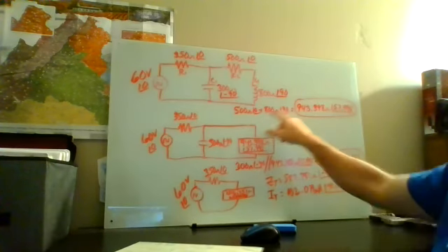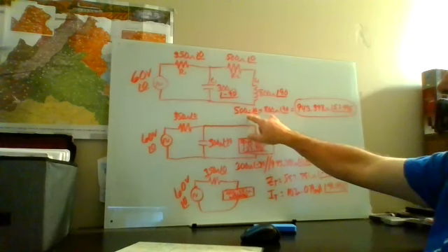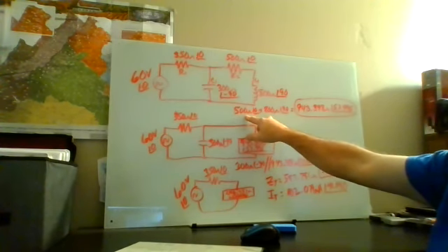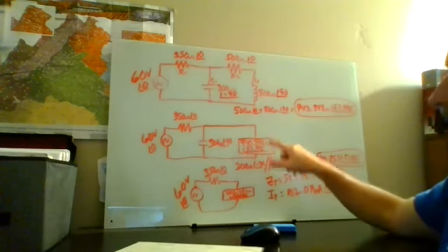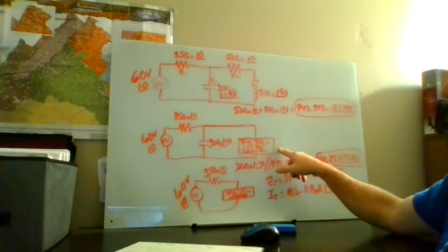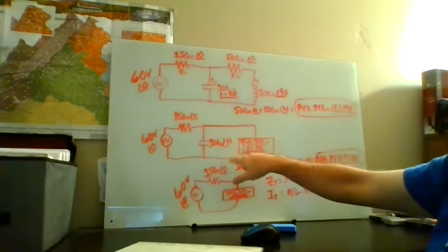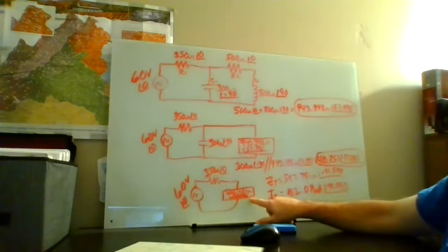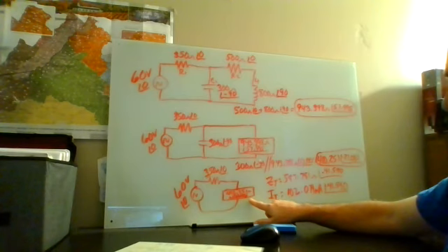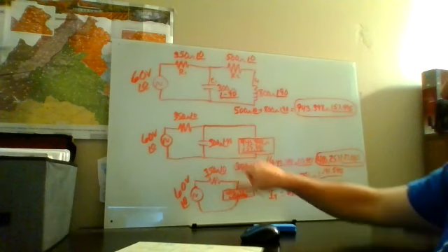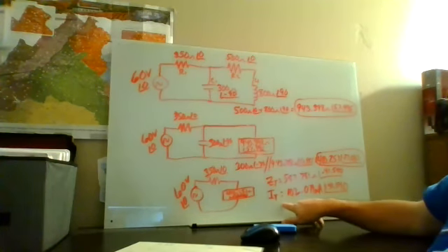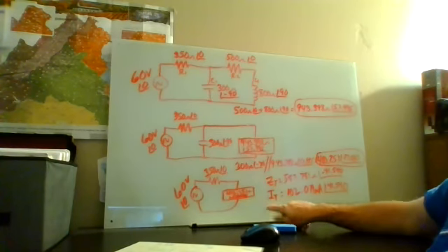Well, now I got a box. I go back to what I circled. How did I find it? These two in series. What's constant in a series circuit? The current. So I'm going to take this current and put it up here. But before I do that, I'm going to add these two currents together to make sure I got where they came from, which was down here. That current was 102.079 milliamps at an angle of 41.540. So when I add those two currents, I should get that current, which is my I total. If I did, I'm good.